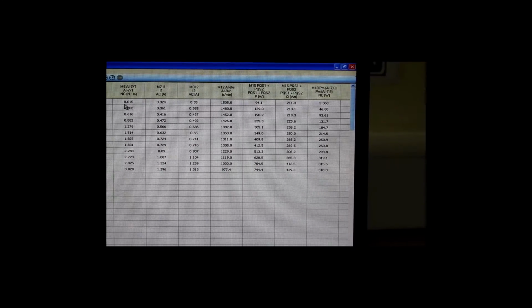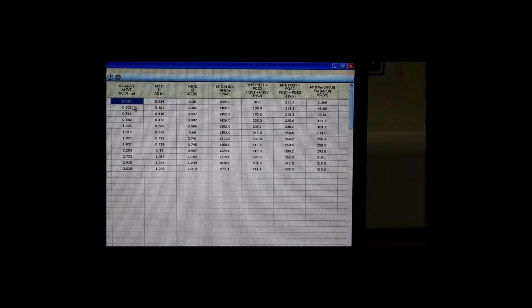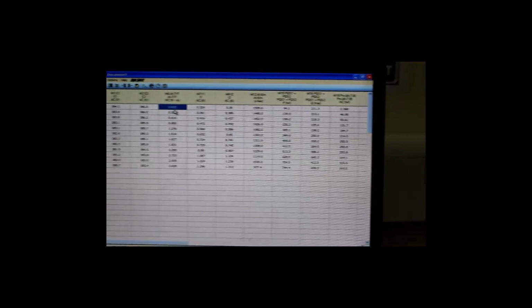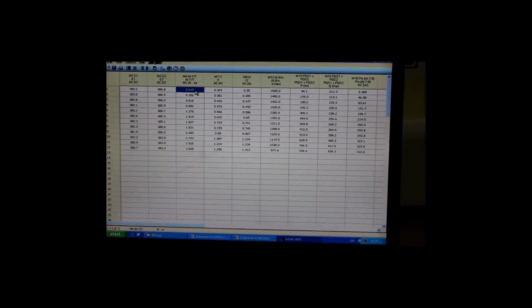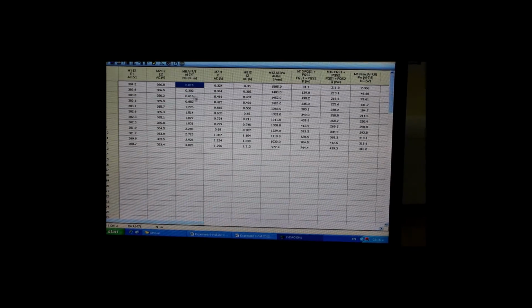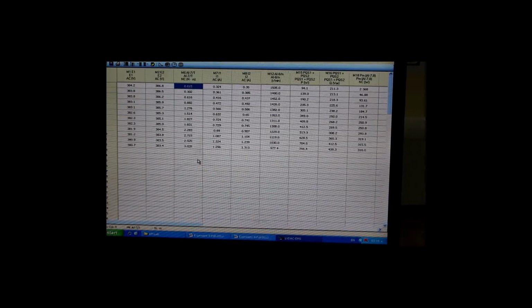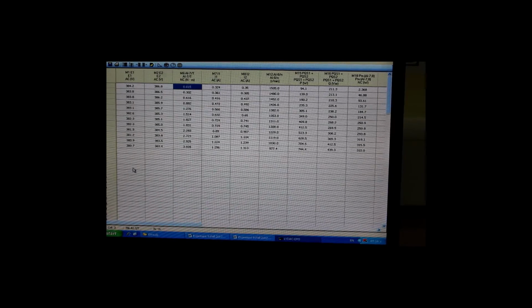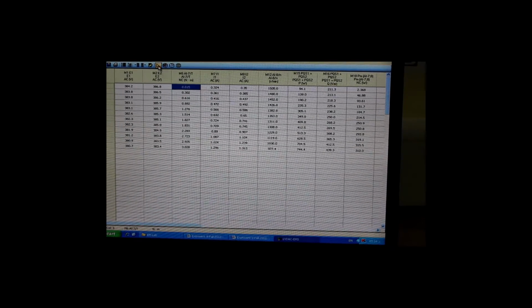I should start from 0. Okay. See, now I should decrease the torque. Start from 0. Now it's 0. So I should measure, add 0.3 Newton meters each time, and take about 10 measurements. So I did 12, so it doesn't matter. And take the graph. I already took the graph, but let's do it again with you guys.